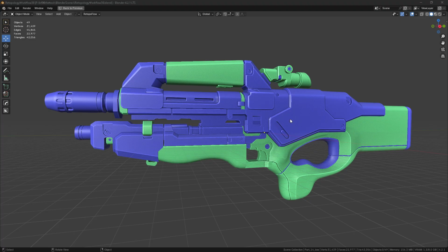Okay, let's break it down. So if we were working on a character, we'd give the skin on the face a higher texel density, since it's exposed and often close to the camera, right? Meanwhile, we could afford to use a lower texel density for the chest, arms, and legs, okay?